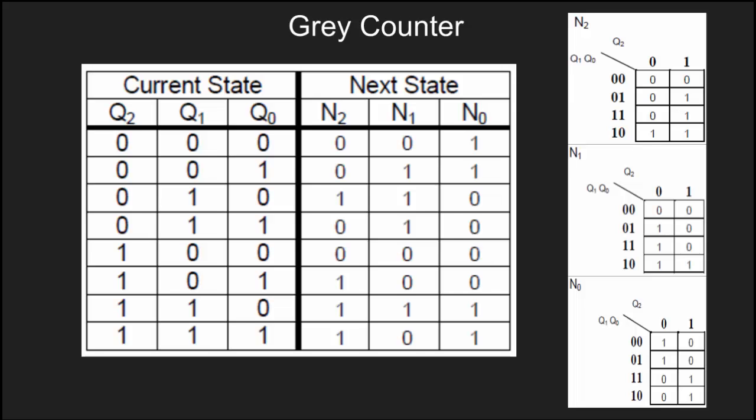The gray code counter has a slightly more complex transition table. It can trip you up if you don't watch it. Instead of moving sequentially, which it almost does, it bounces around a little bit, so you have to carefully follow from current to next state and from next to the following current state. So here we go from 0 to 1, and then from 1 to 3. So we have to move not to the next current state, but to the third. So 3 then returns to 2, and 2 to 5. So it begins to jump around a little bit, so you just have to pay attention.